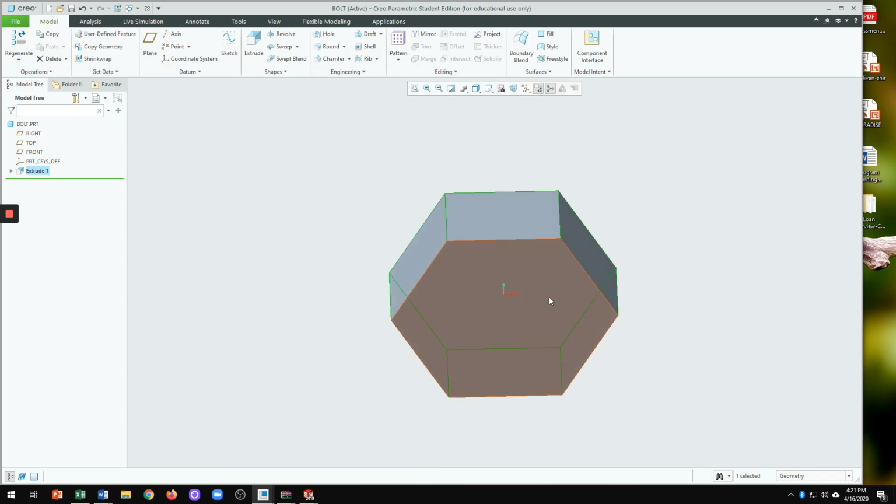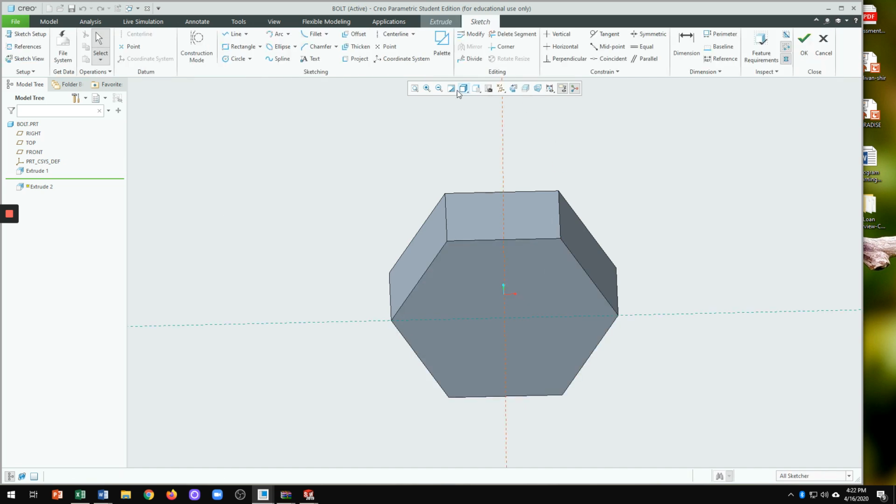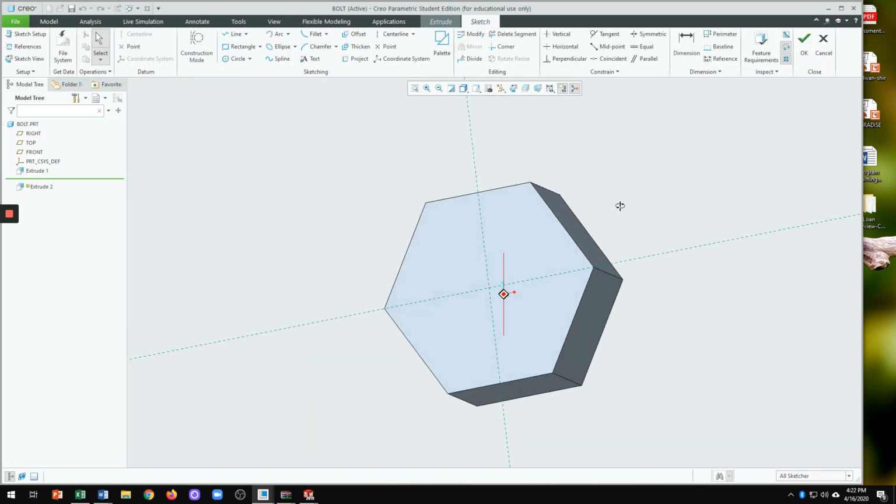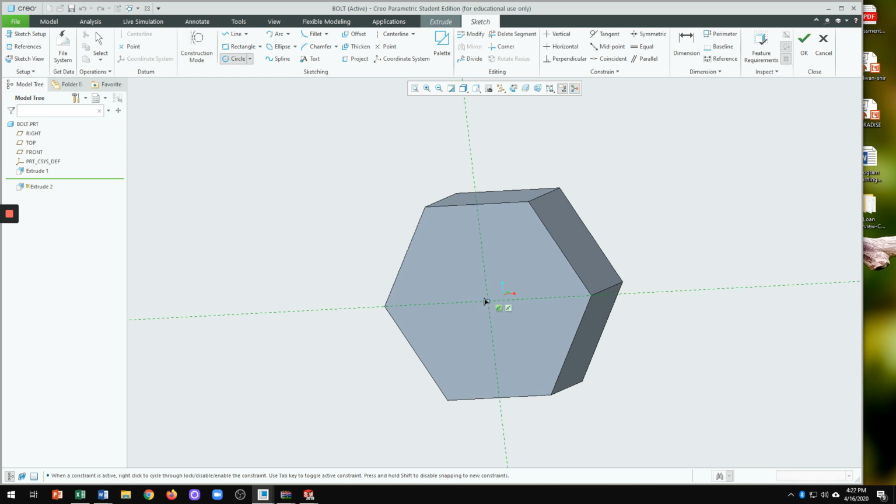Now this is the bottom here. Okay, and we're going to extrude, click on the bottom surface, and we're going to create a circle, and that circle has a diameter of 48. Okay, 48. Then we can just extrude that. The amount of extrude should be 470 minus 30, so it will be 440 from this base. From the top would be 470.